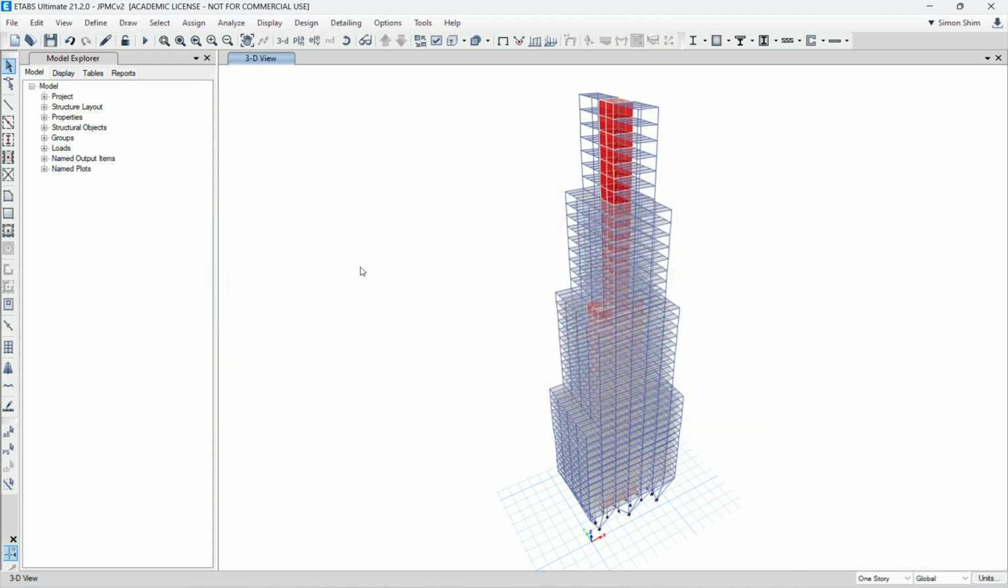Now the thing is, we also need to tell ETABS something else, because the building is discrete, with floors. We usually calculate the wind loads based upon, as I said, the wind pressure times tributary area. So we lump each wind load at each floor level. In order to do that, we need to let ETABS know what our building width is, X direction, Y direction. They have to understand width and height,